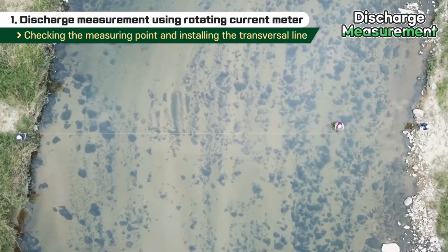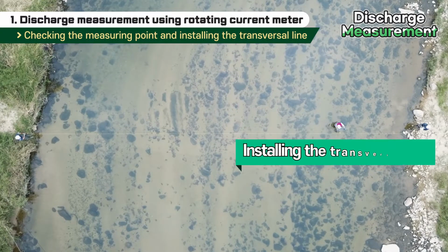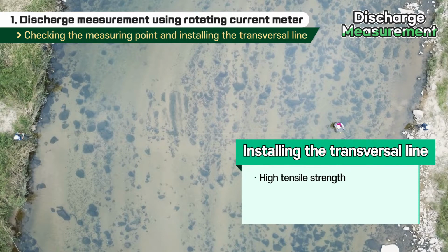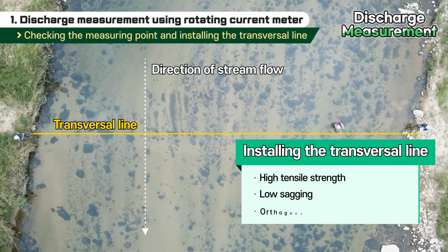Having identified the measuring points, the transversal line should be installed to set the water surface width and gap between the measuring lines. The transversal line is made of high tensile strength and low sagging materials and should be installed in an orthogonal direction to the stream flow.